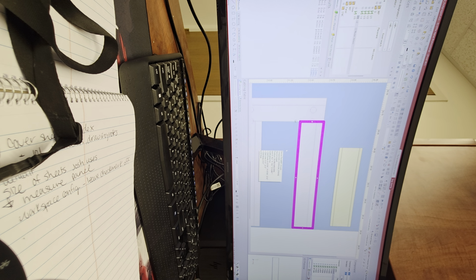Right click on U4 in the device tree structure. Say unlock. Yeah, unlock object, top third one. Yeah, I think there was an accidental selection. Okay. Yeah, we just accidentally locked this U4. That's why it was shown gray in your device tree structure.